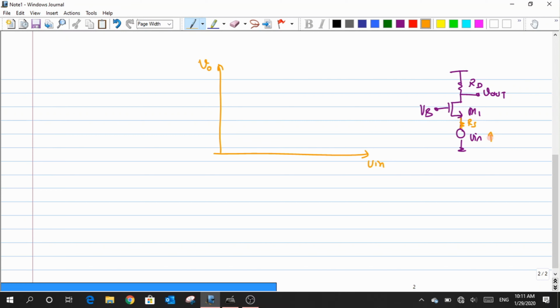So I have a potential difference across this VGS, let me remove this RS. Why include that? Okay, so let me try to deal without RS. Whatever the value of VB that I have entirely falls across this VGS, as it is when I have Vin equal to 0. Now in that case, how will I define my output? Is there an existence of current? Yes, obviously there is an existence of current and the value of that current would be large. So that is for sure.